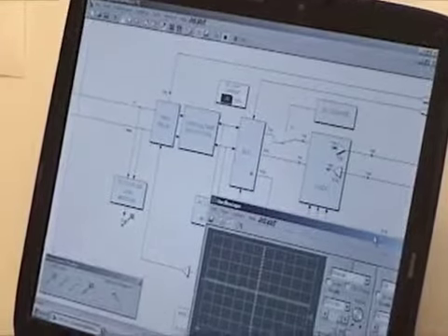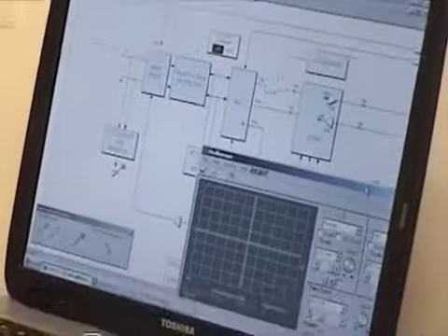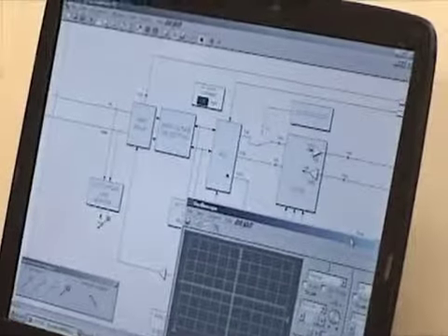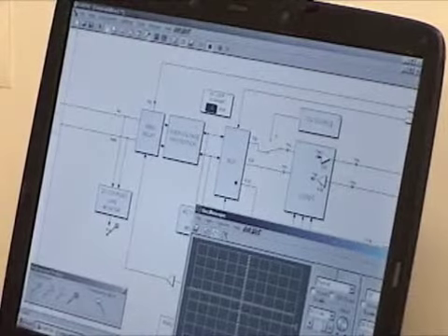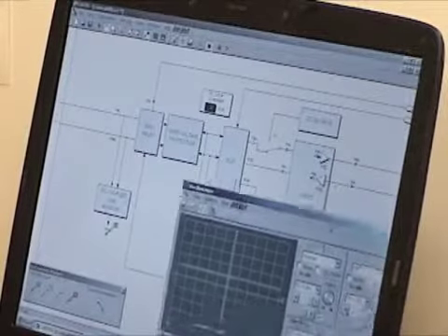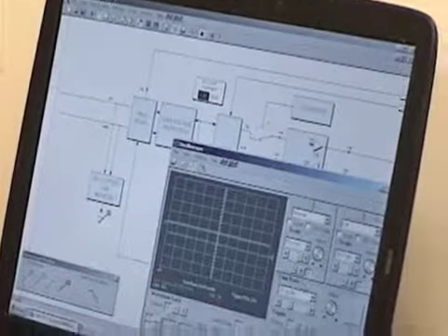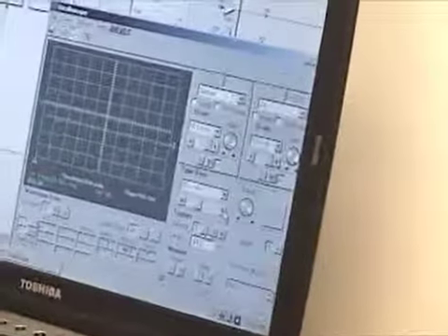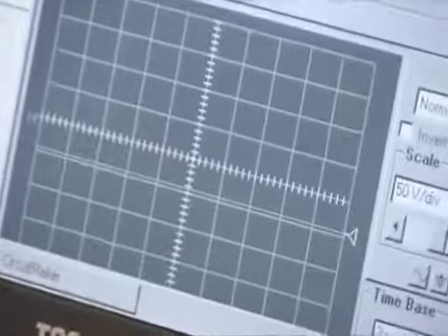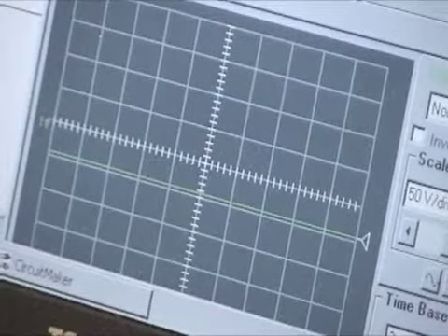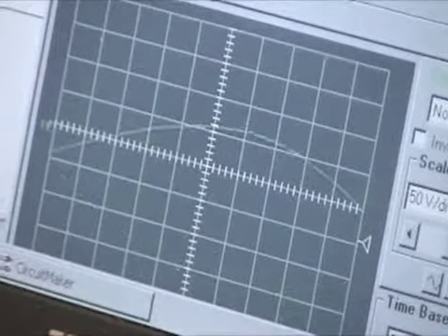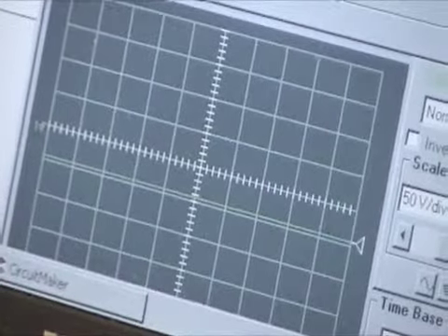Now the next thing I want to demonstrate is what happens when one phone rings another phone. So what I'm going to do is leave my probe there, and I'm going to look on the scope here. I'm going to move the time base up a little bit. And I'm going to ring the phone, and we're going to see the ringing voltage on the scope there. So let's see, 5551001. And now I'm ringing the phone.